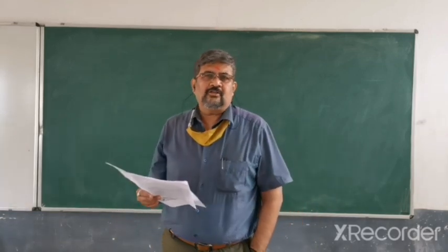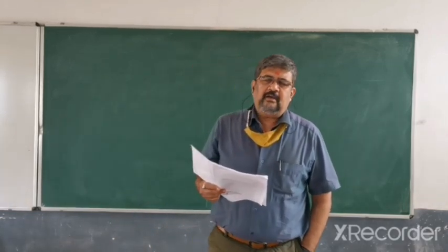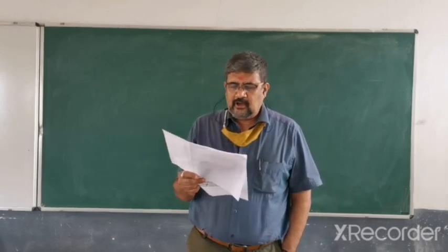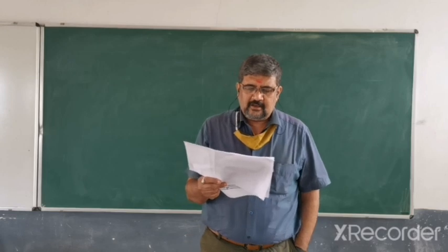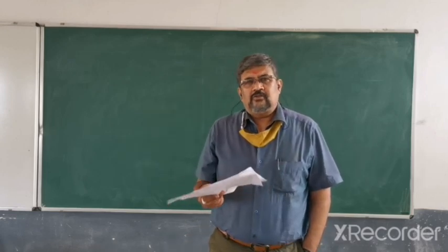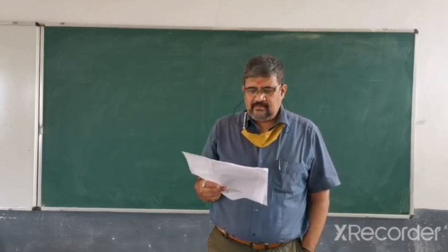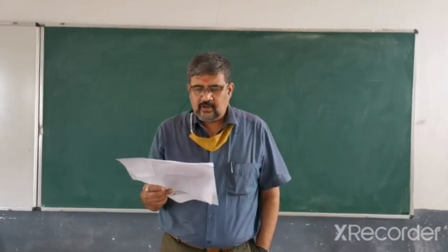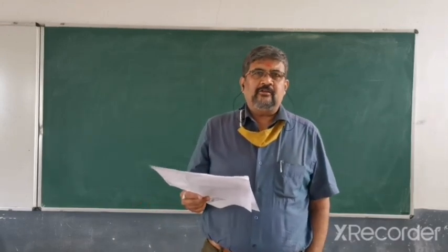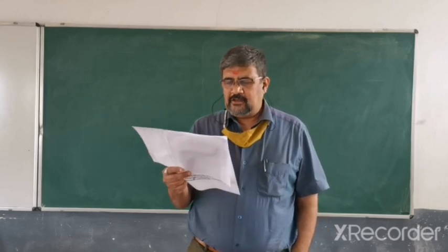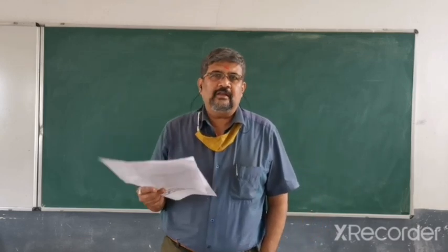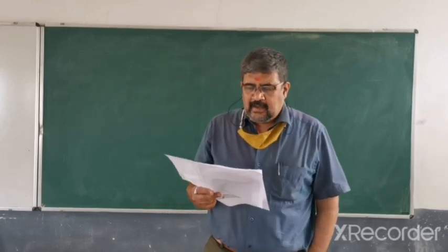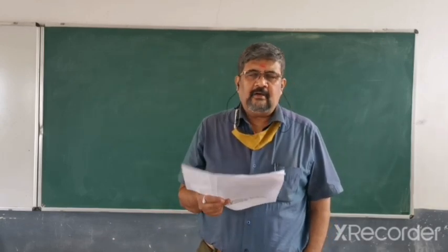So there is no question of W minus S multiplied by 9.81 and so on. That value has to be taken directly. That is, torque is 200 Newton meter. So there is no question of calculating W minus S into R. T value is directly given. You can use this value of T, which is 200 Newton meter, in the equation. Brake power is 2 pi N T by 60 into 1000, and find out what the brake power is.